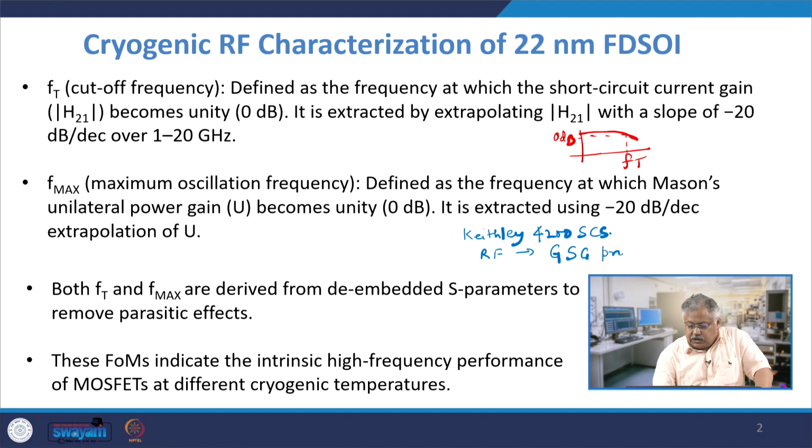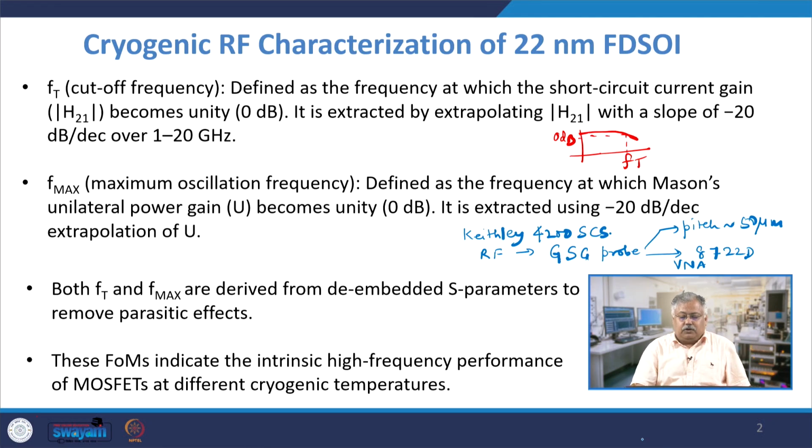The pitch of these probes, the distance between the two probes, is approximately 50 micrometer, and they used an 8722D VNA, vector network analyzer, for extracting the S parameters.